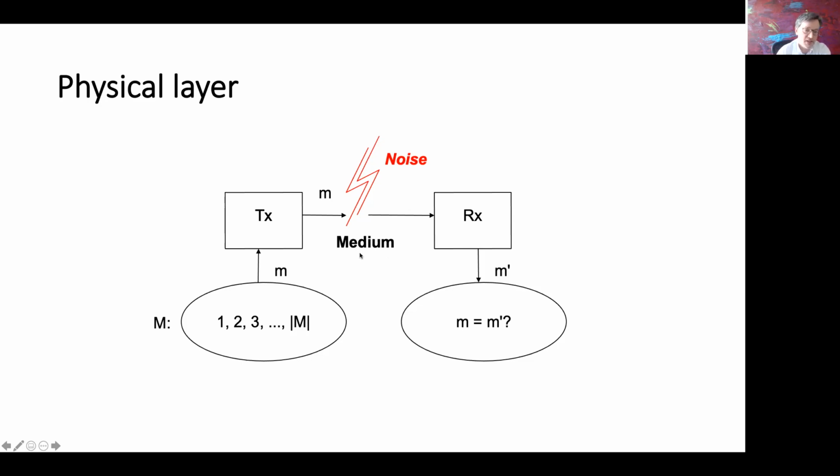So we know that in conventional communication systems, the transmitter is a modulator and antenna. The medium is free space. The noise is additive white Gaussian. The receiver is a receive antenna and an amplifier. Actually, the noise occurs in the amplifier at the receiver, but we can consider that part of the channel. And then we are very familiar with ways of guessing what the message is at the output of the additive white Gaussian noise channel.